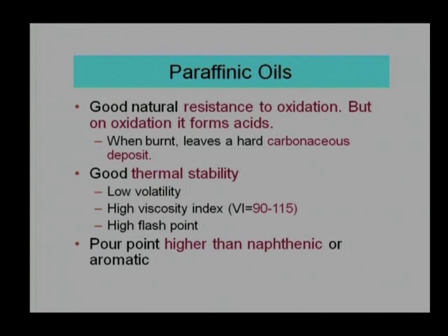So, lubricants are used to reduce friction and wear, but if we choose a lubricant which is not thermally stable, it burns at high temperature, the temperature may be 150 degree, 170 degree, 190 degree, then they will make deposits, and with the presence of deposits the clearance will reduce. In addition, there is a possibility of these hard deposits acting as abrasives, causing more and more wear. So, we select the lubricant for a good reason, to reduce friction, to reduce wear, but because of lack of understanding, if we select a lubricant which is not able to sustain the high operating temperature, then they will form